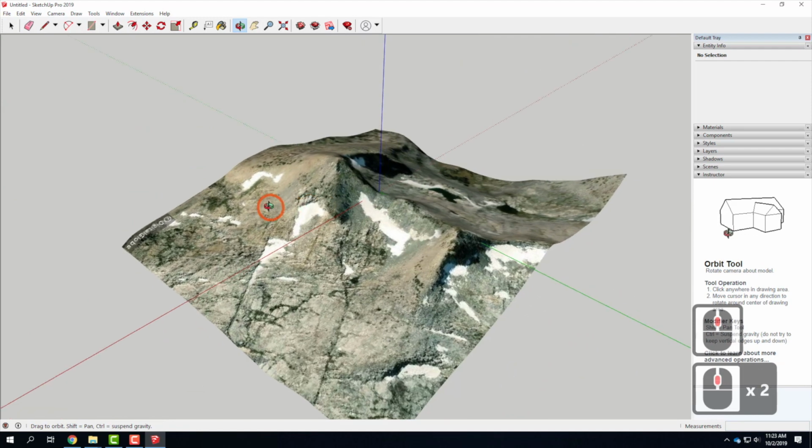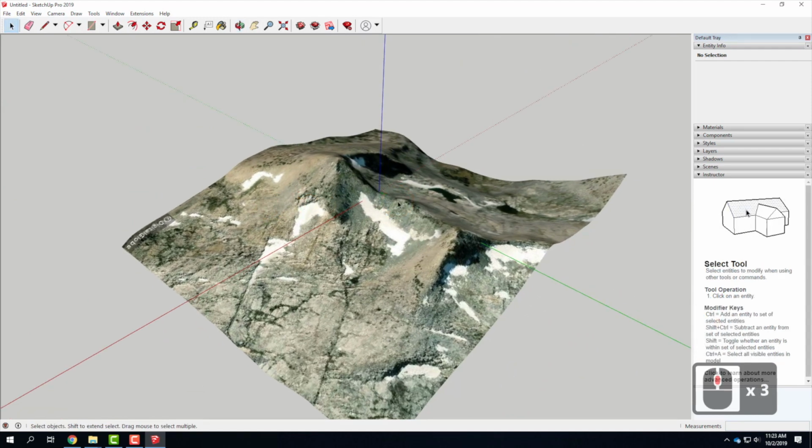That looks reasonable. If you end up picking a piece of terrain and afterwards you say, I don't really like that very much, just create a brand new SketchUp file, go back in, and do a new piece of terrain. SketchUp doesn't like it when you go back and try to grab it again once you've already brought terrain in once, especially if they're far apart. It gets cranky about it. So it's better to just create a brand new SketchUp file and bring it in that way.